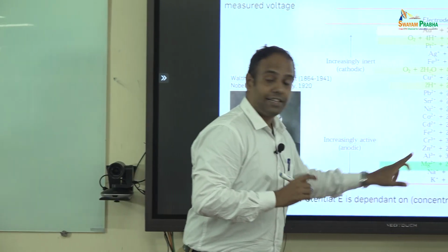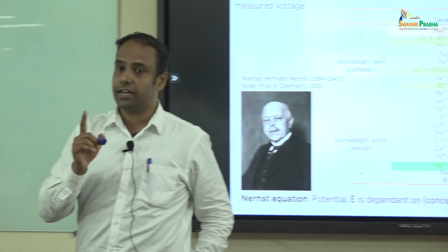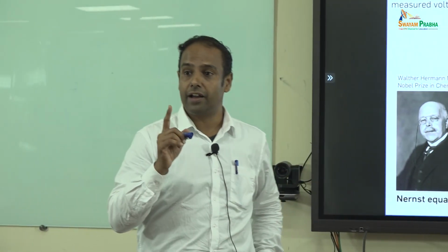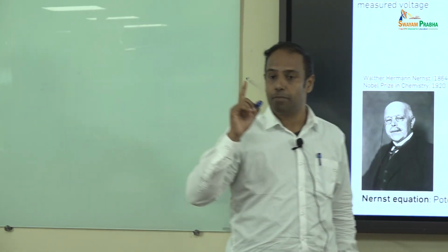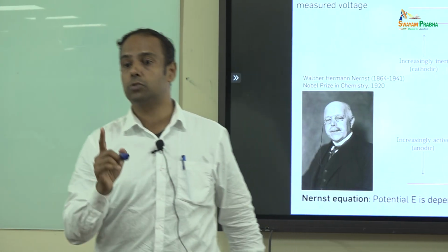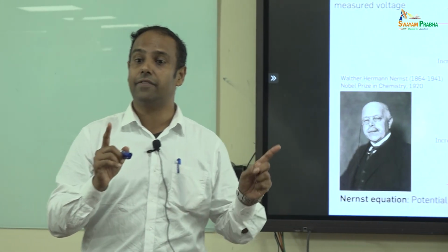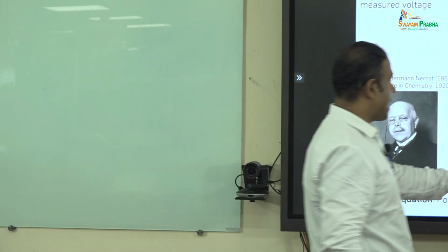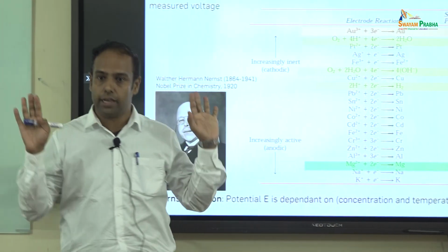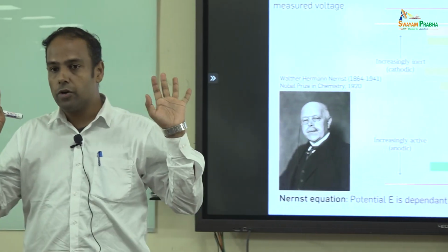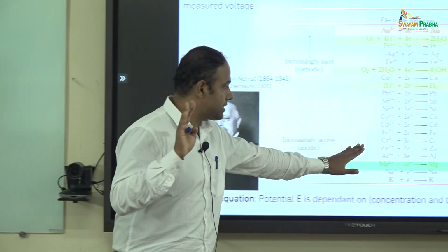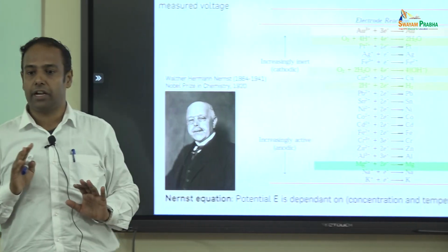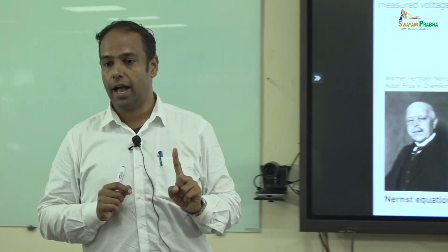So, the protection of iron by galvanization does not depend on the corrosion resistance of zinc, but the corrosion ability of the zinc is what is used to prevent iron from corroding. That means, sacrificially zinc says, I can give the electrons on your behalf, you be the surface where the cathodic reaction happens. Therefore, he says cathodically protecting by a sacrificial anode.